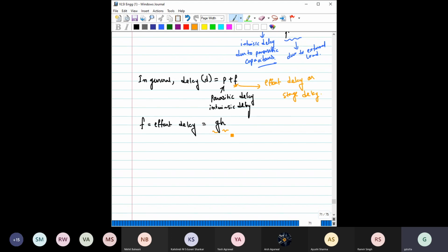What is H? H is the fan out, also called electrical effort. This H can be written in general as C out by C in.